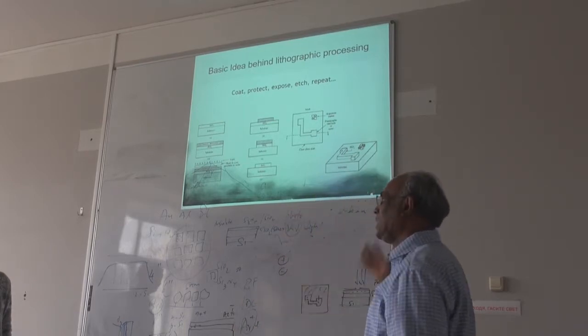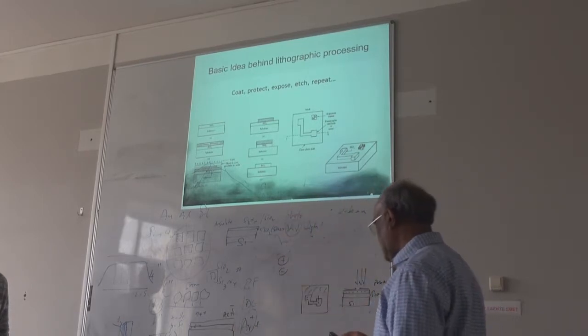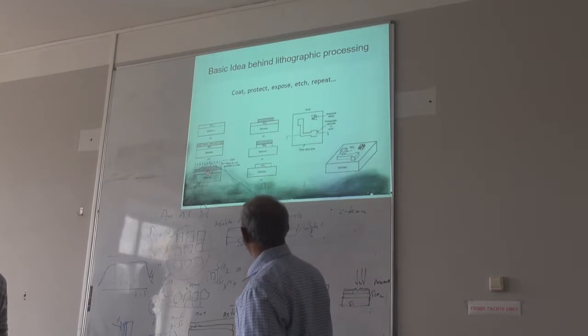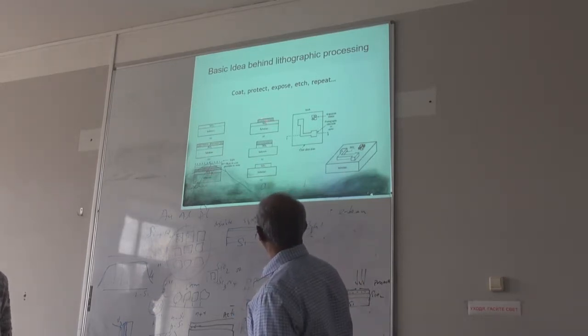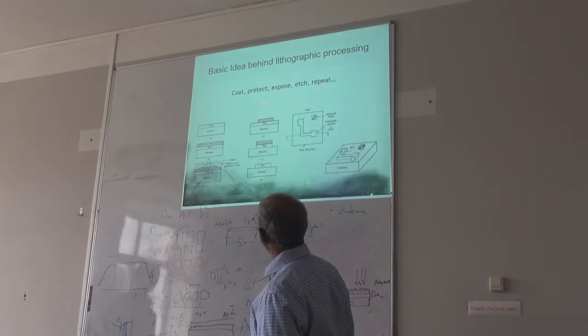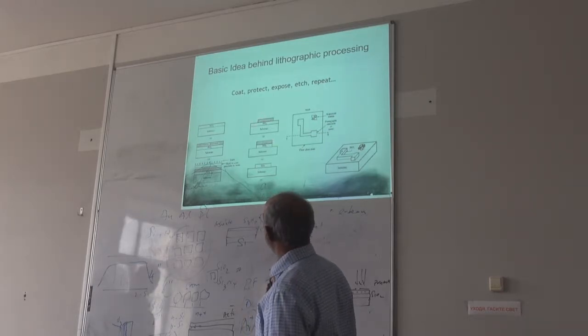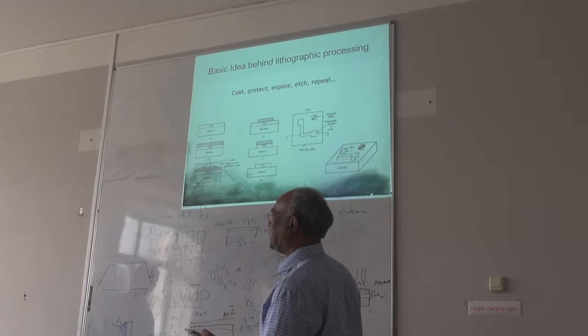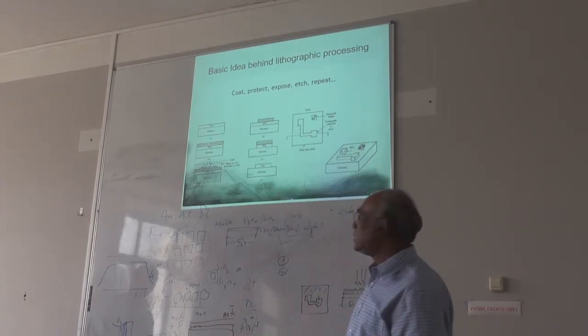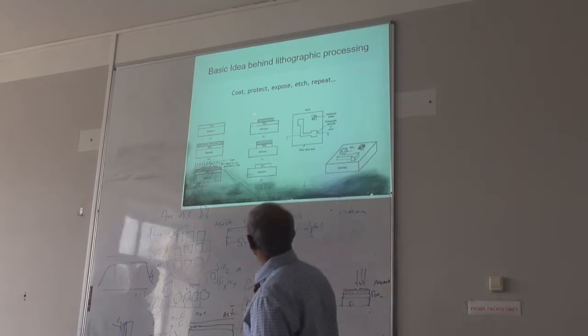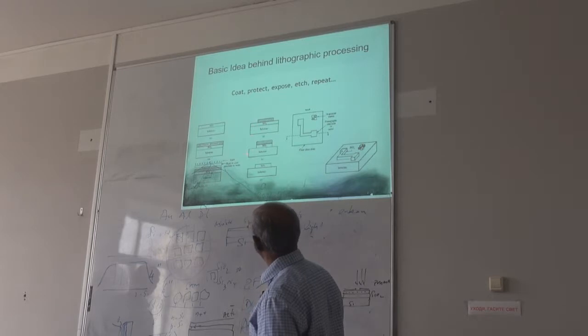So that way you can do whatever patterning you want, right? So in this case, actually, see now you expose this one here. So this is the exposed part, right? This was exposed here, but this was not exposed. So this is a negative photoresist. So now if I put this one in a solution called the developer, it removes only the photoresist that was not exposed here.